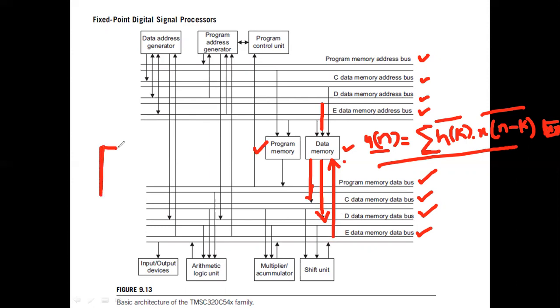Moreover, nowadays this memory is called dual access memory. Say you have a RAM, what is the usual method? You give the address on the address buffer and read the data on the data buffer. So in a cycle technically you can read only one data. But nowadays you get dual access RAMs, where the hardware is so optimized that you can read two operands at a time, or read and write at a time. Nowadays you might have seen DDR RAM, double data rate, something like that.